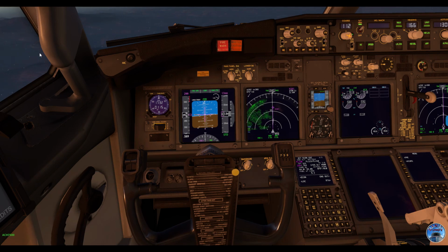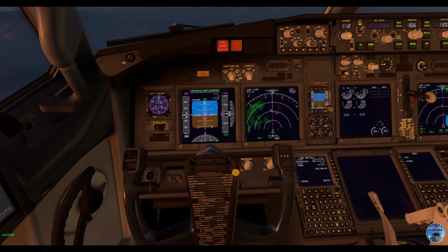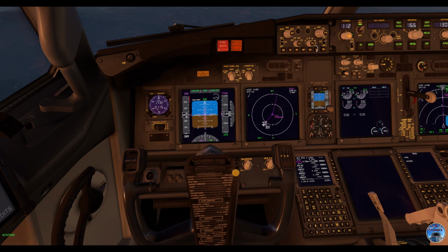First we program now our FMC for arrival. We have to enter the rest of the route. LOWW arrival using ILS runway 11, transition Ballard 3 Kilo, and the arrival is Nixie 1 Whiskey. Perfect. Execute. And then we check the legs page and the navigation display to flight plan and step through. Okay, the route looks good.